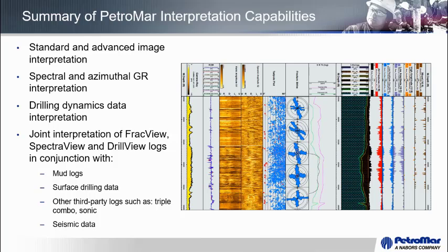And this image on the right also shows that we can look at the fracture density along the hole, looking at how that fracture density varies, and also to correct, particularly where we've got more than one fracture set, we can do a correction for the downhole attitude of those fractures to correct for how many of each fracture types are actually seen to try and correct for the borehole bias that's created there.